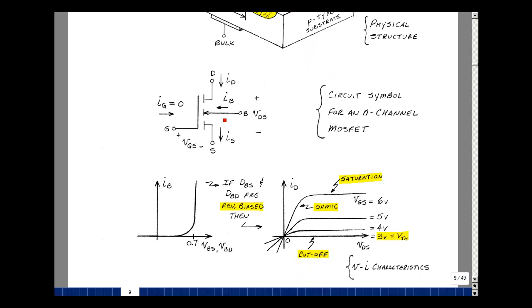The diode that's between the bulk and source and bulk and drain has a VI characteristic with a forward drop. But we're not going to operate it here. We're going to operate it where it's either negative or just slightly positive. And if you do that, you then get a family of curves. Starts out and levels out. And as the gate source begins to decrease, the current begins to decrease. And eventually the current will go to 0. And that particular voltage is called the threshold voltage.